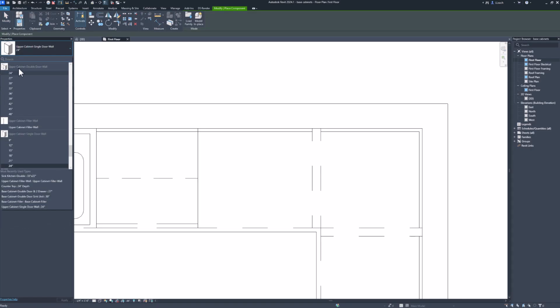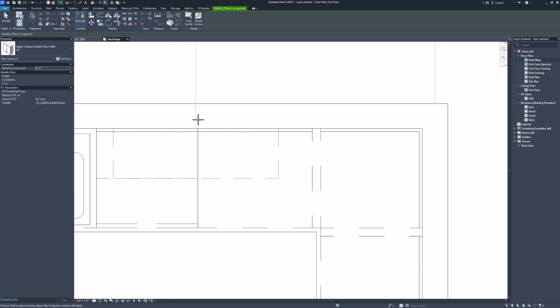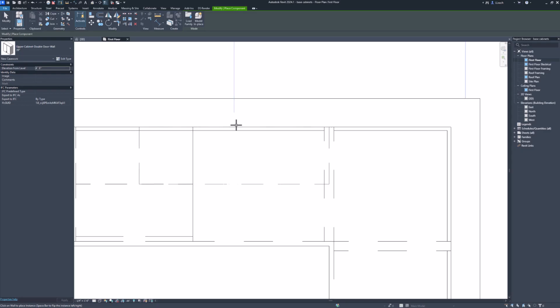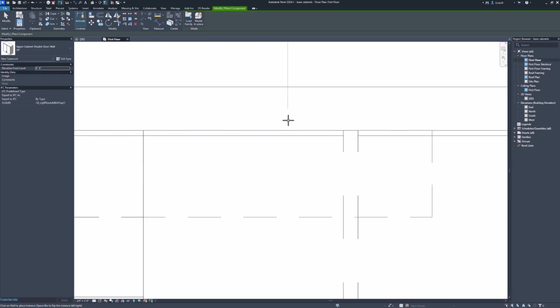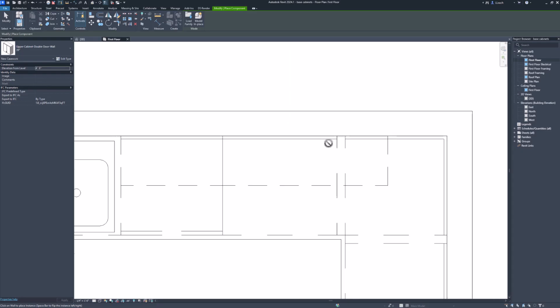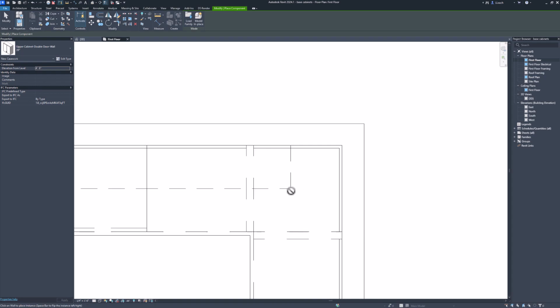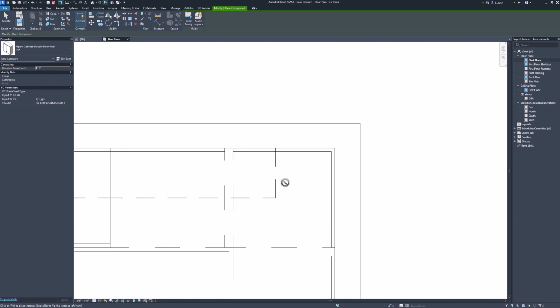So, a 39-inch upper cabinet, this one, because I've already done the math here. I know that's kind of a wide cabinet. You could put two cabinets there if you want to split them up. It just needs to equal up to 39 inches, however you want to do that. But anyway, I'm just going to line that up. And then over in this corner, I don't want these cabinets opening up into each other, so I'm going to put a 2-inch filler on each side of this corner.